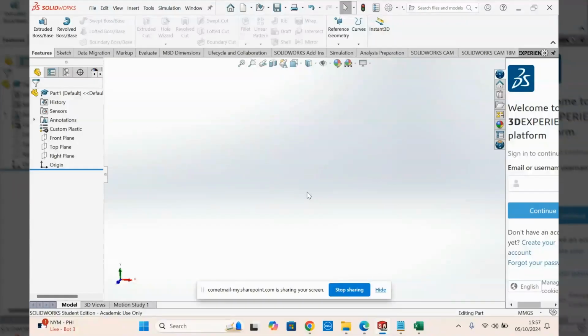So in this video, I'm going to show you how to do aerodynamic surfaces. The specific one I'm going to be doing is the vertical tail, but this process is identical for doing wings or horizontal tails. It just involves importing a different airfoil and then extruding it a different amount. And I'm going to demonstrate how to do this for the vertical tail I'm using. You can follow the same method for whatever airfoil you're wanting to do.